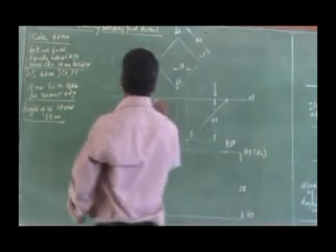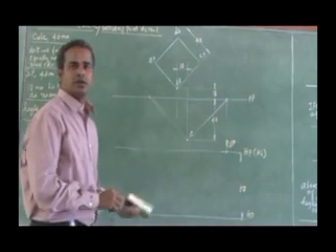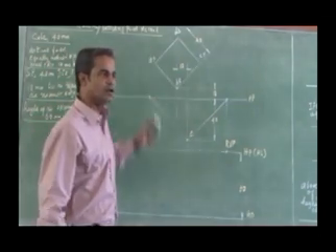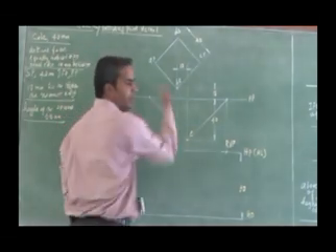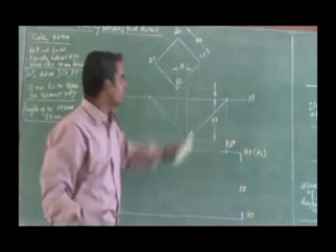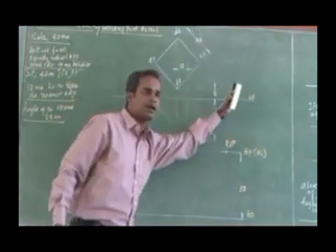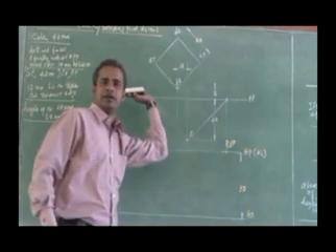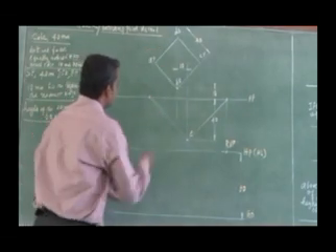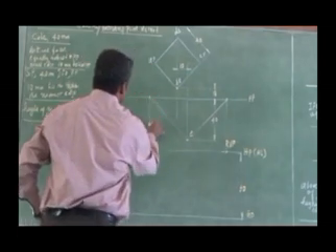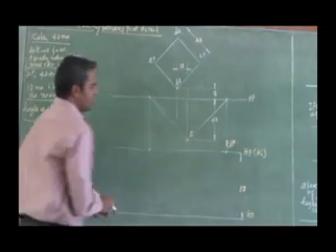This is a parallel line I am drawing. Where it meets, this is parallel to the left face, that is BQAP. Use your drafter fixed to this face and draw a parallel line. Then, by dropping this to the horizontal line, draw a projection line to the horizontal line.